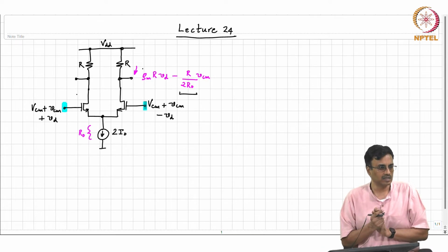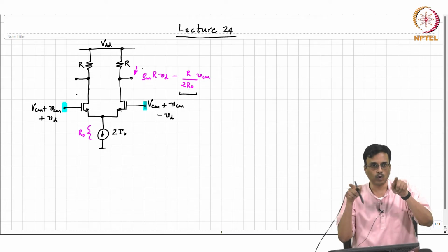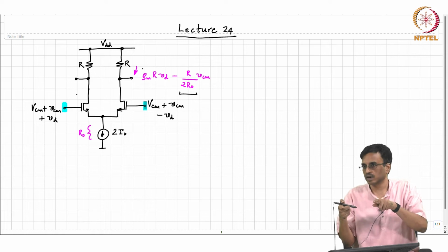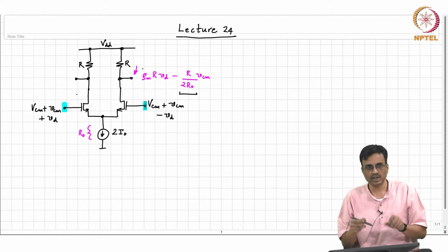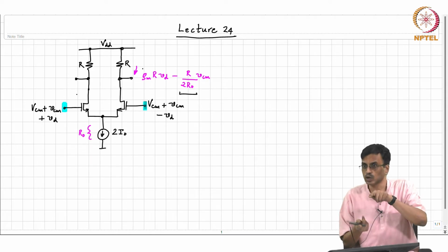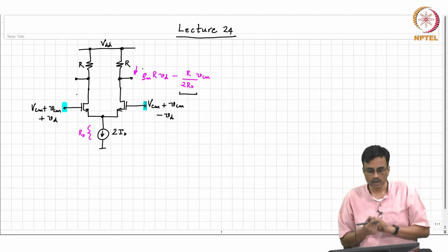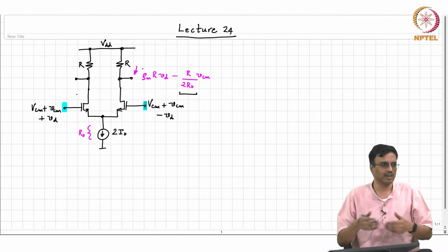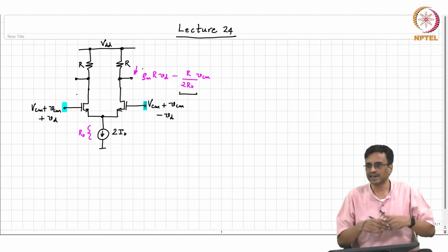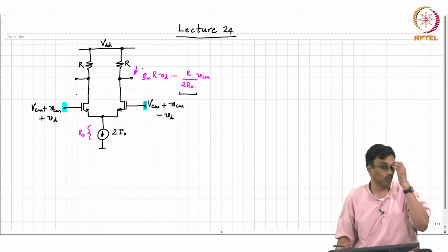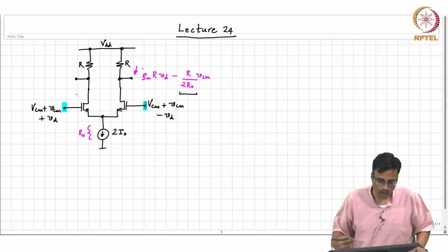So, it has taken two floating voltages, taken the difference, and converted it into a larger voltage, and that resulting voltage is referred to ground. Then, once you want to amplify that, you can put another common source amplifier, or if that gain is not enough, another common source amplifier and so on to get as large a gain as you want.